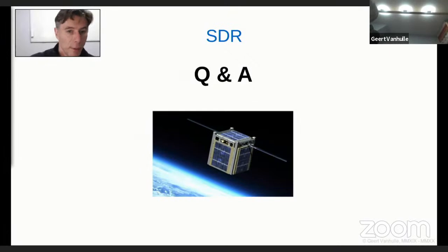If we take the harmonic signal in the output signal, which is maybe an easier example to understand, instead of filtering the output signal, what we can do, and this is the huge advantage of software-defined radio, is in the digital processing, we add the inverse signal of this harmonic digitally to our sample range.